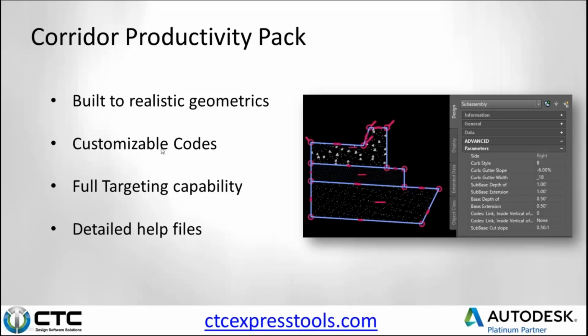Customizable codes is a big thing. Once you really get into corridor modeling and you're trying to dictate quantities and the way sections label and different things like that, the coding, be it point, link, or shape code, starts to make quite a bit of difference. And so for this one, for example, you've seen just a couple codes that we've decided to customize. This is the inside vertical. I'll show you how this might work.